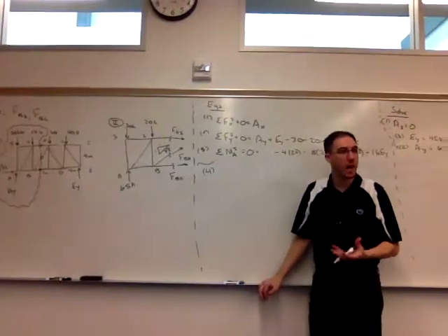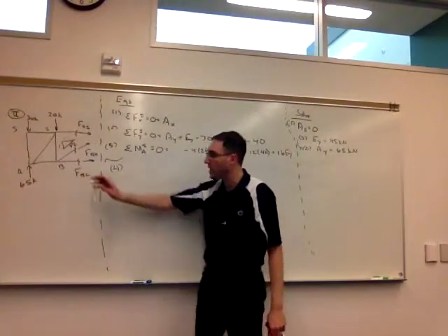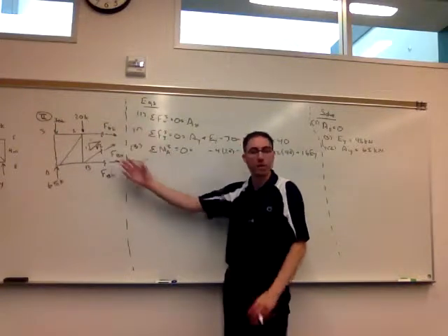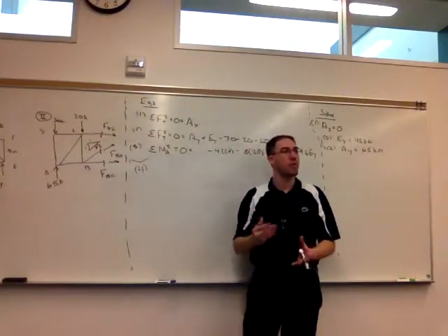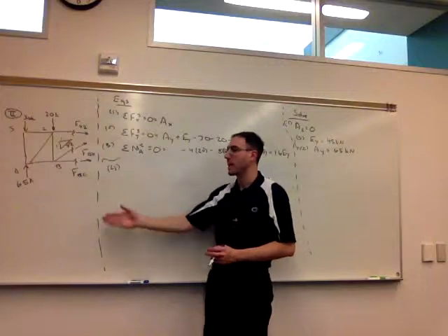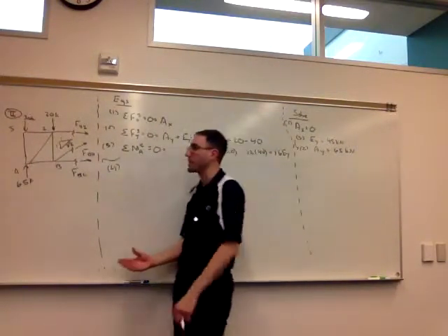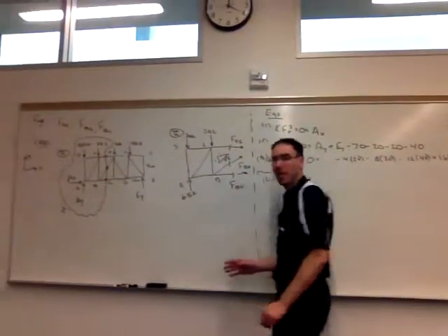Again, I'll reiterate, it's not always possible to get away with just one cut that will go through everything you want, but you want to start with a section, and then you can add more sections or then move on to pin diagrams to get the rest. It can still save you time overall compared to going all the way through with analyzing the pins.